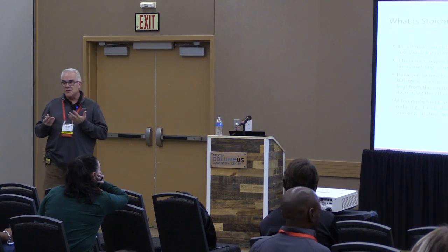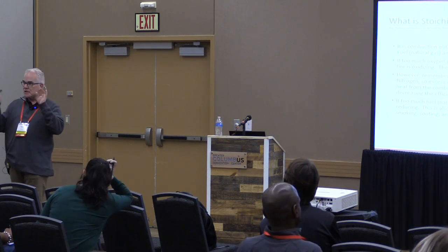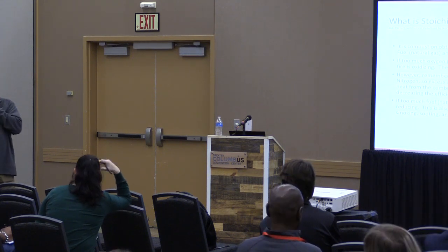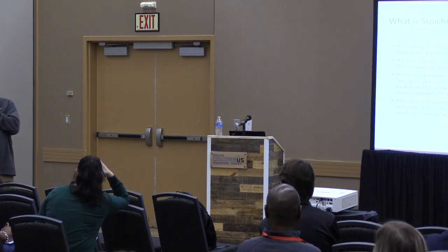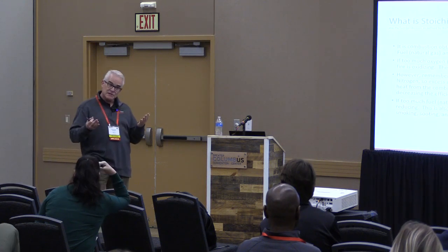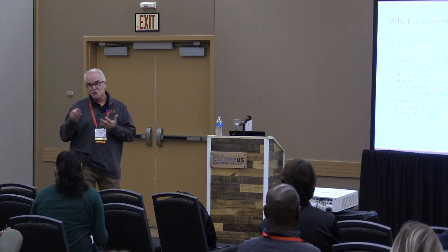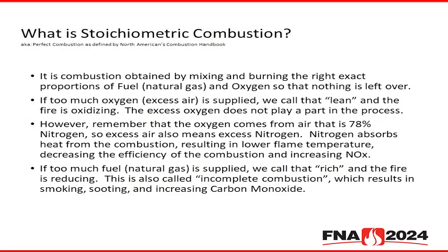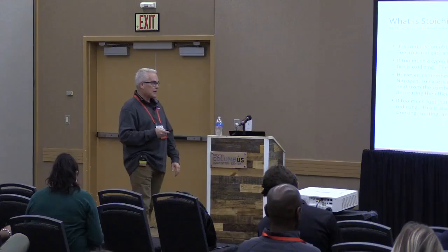But we often walk into companies and say, how are your furnaces? They're running fine. They're tuned okay. When was the last time you tuned them? When did Pete retire? And so it's maybe been years, but they're still making flames. The flame's not too blue or too yellow, which we find is how people are tuning, by color. But if you look around the burners and there's evidence of a carbon snowstorm, that's a pretty strong indicator that you're running too rich, which is what we're talking about here.